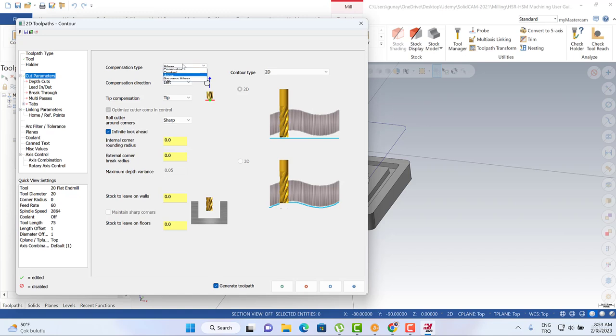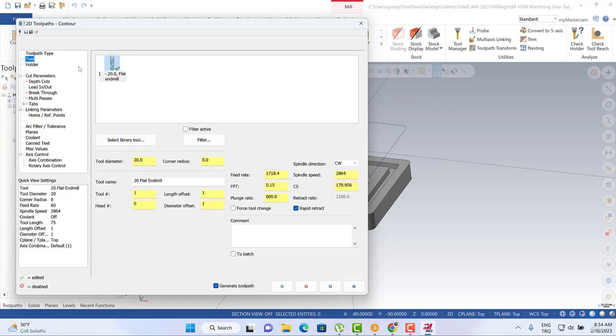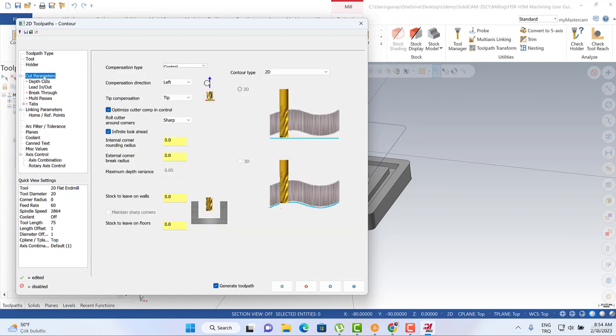And after that, if you intend to use the control, actually, when you write control, you need to write your diameter offset in your CNC. And also, you can also use your wear parameters. So when I am selecting control, my tool diameter is not calculated by MasterCAM. So this is the quite important part. So I'm gonna turn to the wear here. So when you turn to your CNC, you can easily organize your tool wear by using the wear offset number.